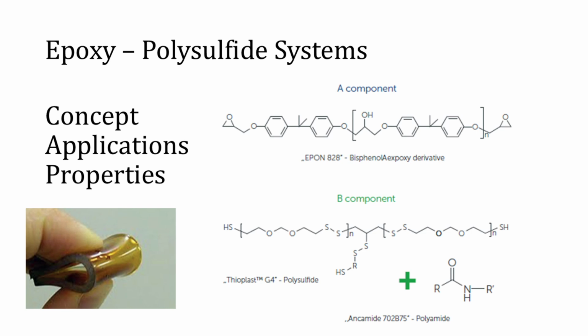Liquid polysulfide polymers find an important role as flexibilizers within epoxy-based sealants, adhesives, and coatings. By carefully balancing the type of epoxy resins, the ratio between epoxy and polysulfide, the curing agents, and fillers, formulators can tailor the final properties to suit specific applications. This flexibility in design allows for optimizing depending on the intended use, whether for enhanced flexibility, chemical resistance, or durability.